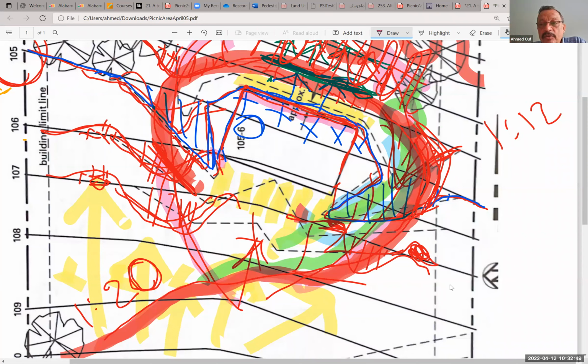The golden rule is we shouldn't move any earth from the site. I mean, all of our cutting and filling should be kind of equal. The balance. Otherwise, it will be very expensive. Only in very rare cases do we allow bringing fill soil from outside. Usually we don't allow that, because we should play with whatever we have without the need to bring something from outside.